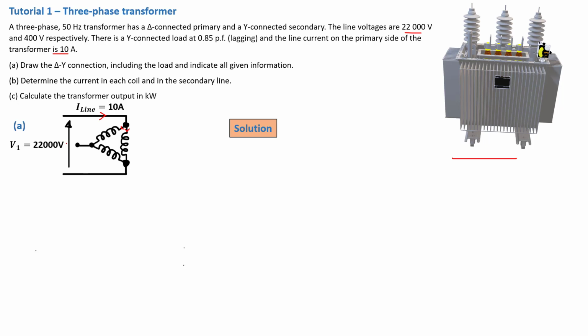So in conclusion, power is transmitted using the delta configuration because of the cost, and also because the delta winding eliminates the third harmonic current and prevents it from flowing into the transmission line. Now let's go ahead and draw the secondary side, which is a star connected transformer secondary.